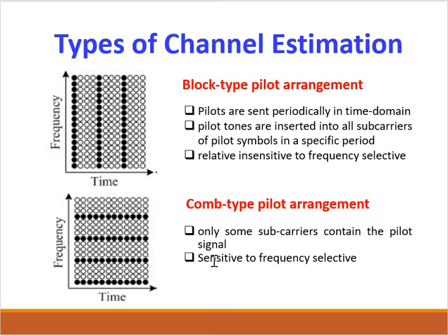And because the training block contains all pilots, channel interpolation in frequency domain is not required, so it is relatively insensitive to frequency selectivity. In comb-type pilot arrangement, only some subcarriers contain a pilot signal, and it is sensitive to frequency selectivity.